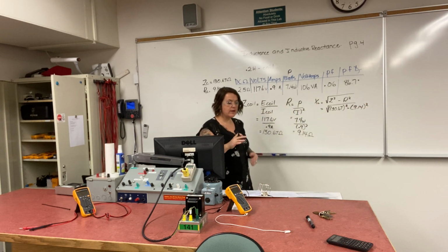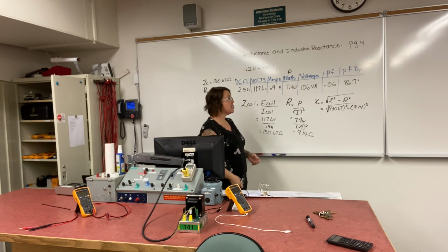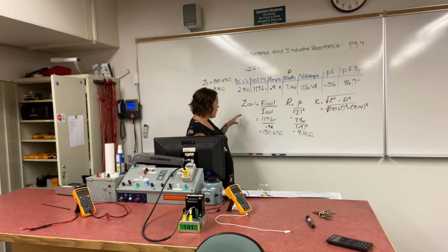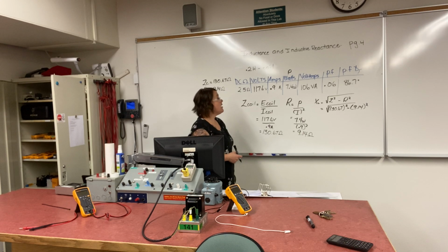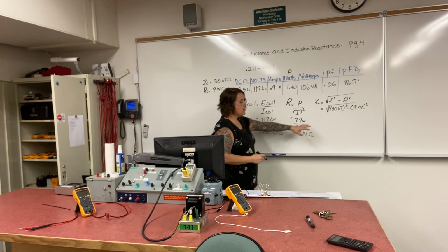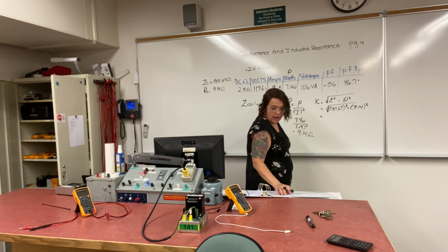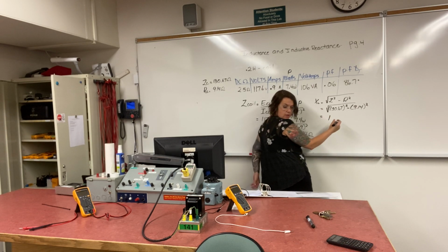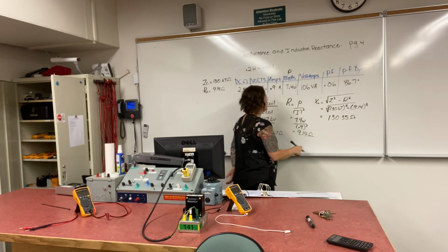And just be aware that we are going to start using these formulas consistently when we get into our RLC circuits. So I don't want you to panic too much about not knowing these off the top of your head, because we haven't really used them very much at all, really. So just bear with me. This is more of an introduction to what will become much more relevant when we start doing our series and parallel RLC circuits. Okay, and so then if I take that, it comes out to be 130.35 ohms. That is my inductive reactance.